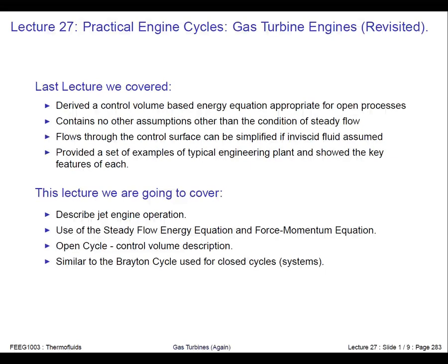So we're going to cover how a jet engine operates and how it's slightly different to a stationary gas turbine. It's a nice example of using the steady flow energy equation and the force momentum equation together, and then we're going to look at it compared to Brayton cycles.